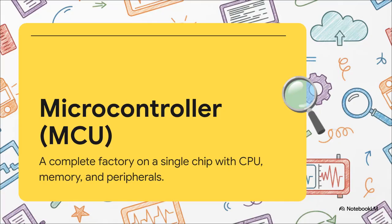Before we even think about writing a single line of code, we've got to get crystal clear on what an MCU actually is. Think about your laptop CPU for a second. It's basically just a management brain, right? It needs an external hard drive, RAM sticks, and a massive motherboard just to function. But a microcontroller, that is a self-sufficient factory completely packed onto a single chip. It's got the management brain, the storage warehouse in the form of flash memory, your active workspace as SRAM, and the shipping docks, which we call peripherals. The whole shebang is integrated into one microscopic package.